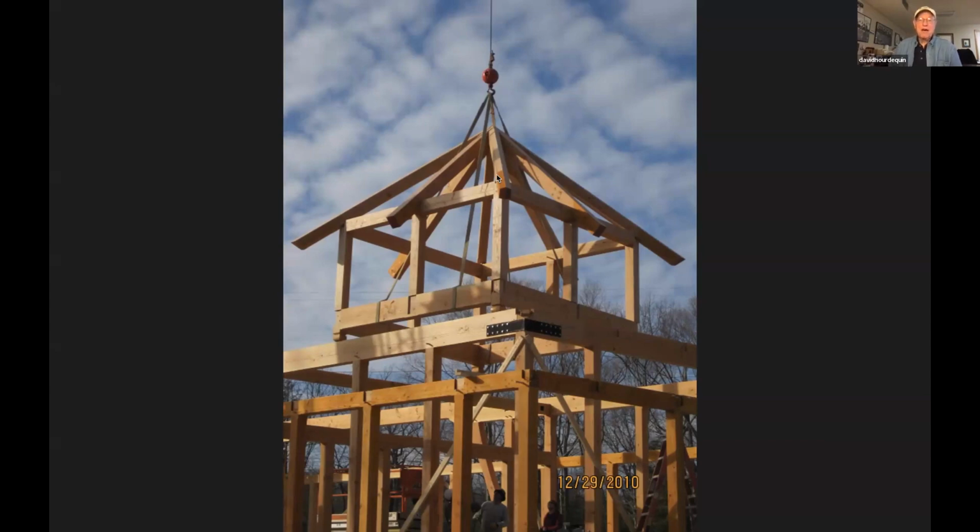I know Jim DeStefano isn't on the line, but I remember, just a quick aside with snow loads, I would go to great detail to analyze the fraction of the ground snow load in a roof system. And Jim says, I always just put the ground snow load up there, all other things being equal, because sooner or later you're going to have drifting loads and you're going to be right back where you started. And he's exactly right.